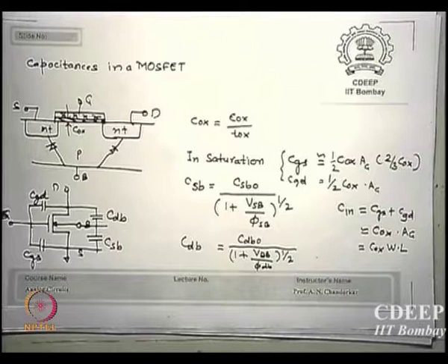These days we actually want less than some angstroms, say 1 or 2 angstroms of oxide. Now we cannot create 2 angstroms of oxide. Can you tell me why? Because the atom to atom bond distance itself will be not less than 1.6 angstroms. So even for one monolayer of atoms, you cannot have that kind of oxide thickness.